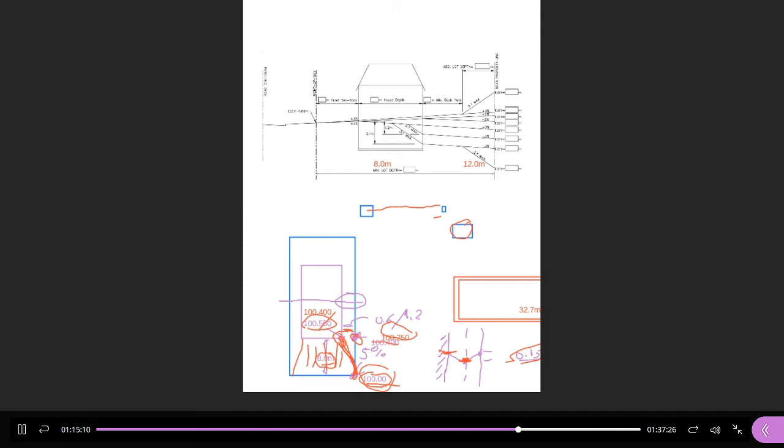I'd have to put a wall here to make up the difference. So when you measure the difference, what's the elevation at the front? What's the elevation at the back? When you know the difference in elevation, if it's lower at the back by more than 3.89 meters, you're going to have a full walkout, a minimum usable backyard, a full slope, and then a wall to make up the difference. Okay, so these are the different grading scenarios you're going to run into.